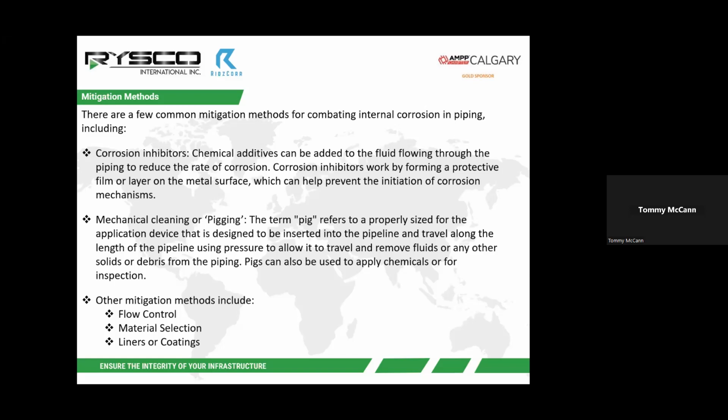And also, especially in the piping and pipeline market within Canada, it's fairly common to use a pig also to deploy your chemicals. So you'll have what's termed a cleaning pig, a fairly aggressive pig up front, and then behind it you'll have a secondary device that will deploy a batch film to the pipe.